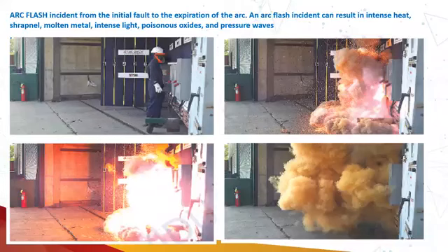So this concept will be tested in the exam: if you determine that the equipment is under normal operating condition, the chance of arc flash is not there, so there is no requirement of PPE and no requirement of an arc flash boundary. But it is very difficult, nearly impossible, to determine whether the equipment is under normal operating condition or not.